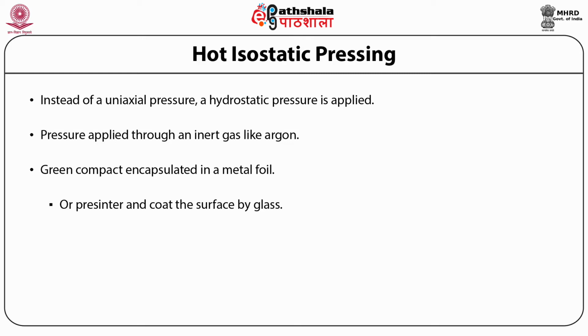Often a part is first sintered in a pressureless manner and then subjected to hot isostatic pressing to remove the remaining porosity and to achieve dimensions with a very good tolerance.